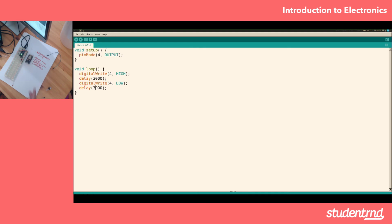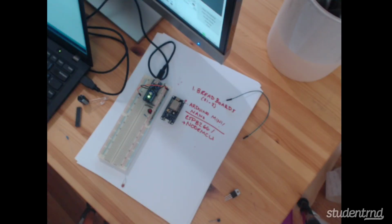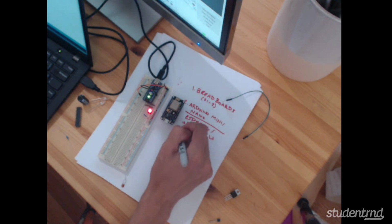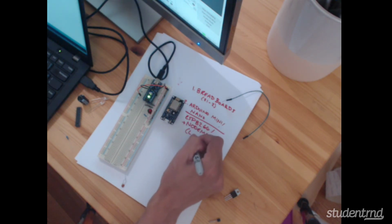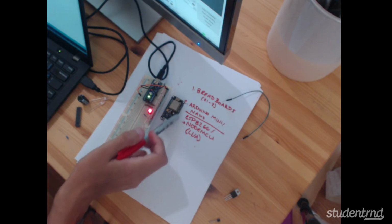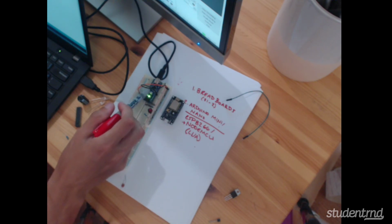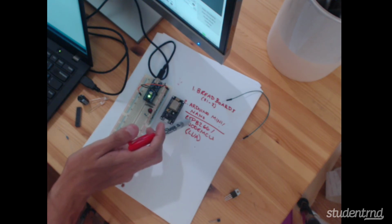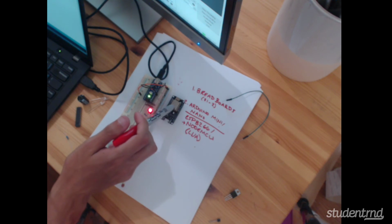And the other thing is, let's switch back to just this. If you remember from earlier, the code looked fairly complicated, right? So instead, you can actually program the ESP8266 in a programming language called Lua, which some of you might be familiar with because it's what you can program a lot of video games in, which is super cool. It has the same concept. It's got the same digital pins. It's got those same analog pins, the ones that can output any voltage from 0 to 3.3 volts. But it uses this chip called the ESP8266 instead of the ATmega, which has this built-in Wi-Fi.